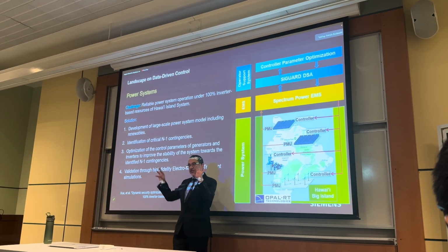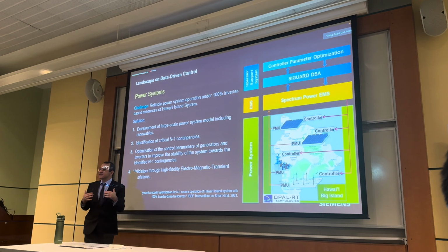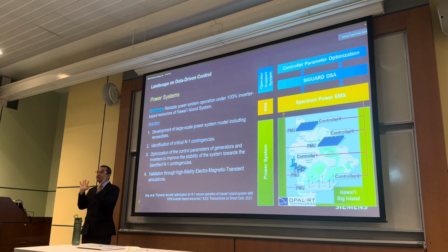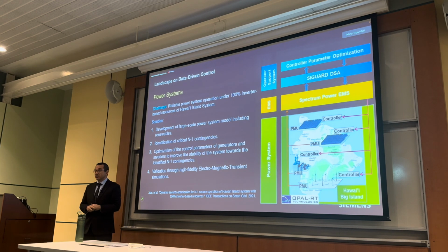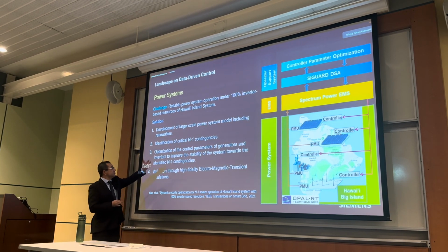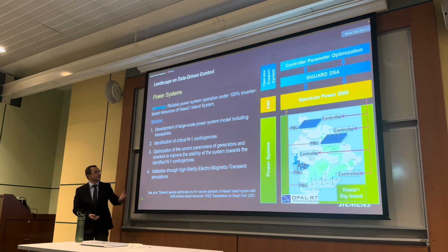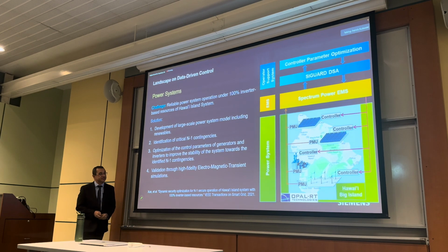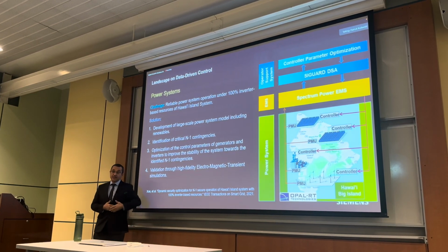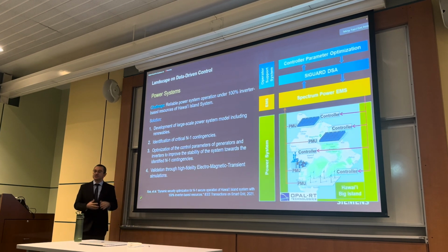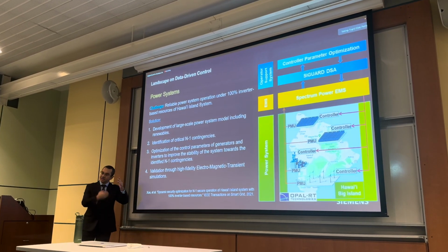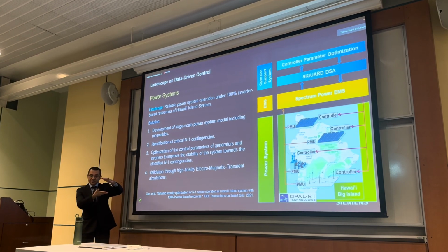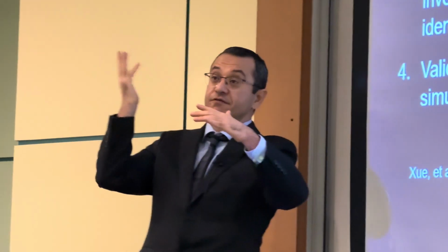Since you have the model, you query different places in a systematic way, creating a list of contingencies. You say, okay, I need to be careful about this and provide a control solution if this happens, because I don't want to go into the dark. That's the main idea. Once you have these contingencies, my work comes into the picture, because I need to optimize the control parameters for them. Remember, it's not one scenario, it's maybe 100, 200, so you need to control across all of them. Imagine hypothetically that one contingency creates oscillations, and another a little bit less. You need to find control parameters, like an aggregated envelope, which minimizes all these oscillations so that people at home don't feel any flickering, etc.